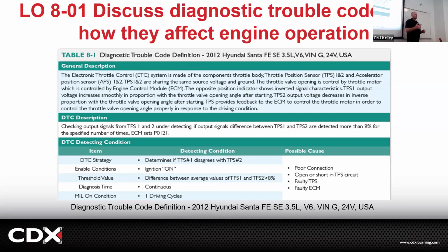What I'm telling you is, this is the drive-by-wire system. You push on the gas pedal, it's not pulling a cable. You're pushing on a gas pedal, the position is being determined by the accelerator pedal position sensor.